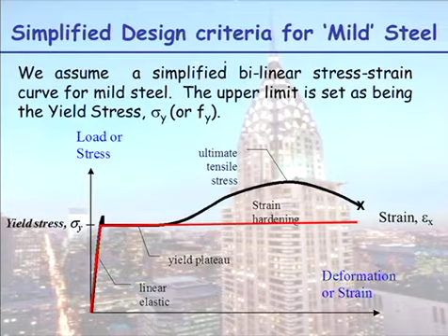Okay, we went through what a stress-strain curve looks like, how you have your linear elastic region, which is where you want your structure to be in the day-to-day life of it. How, if you then do overstress your structure, if you are dealing with a ductile material such as steel, you will enter this yield plateau region, you'll get some strain hardening, and then in the end you'll get failure through necking. What we assume, because when we do design, we are modelling reality.